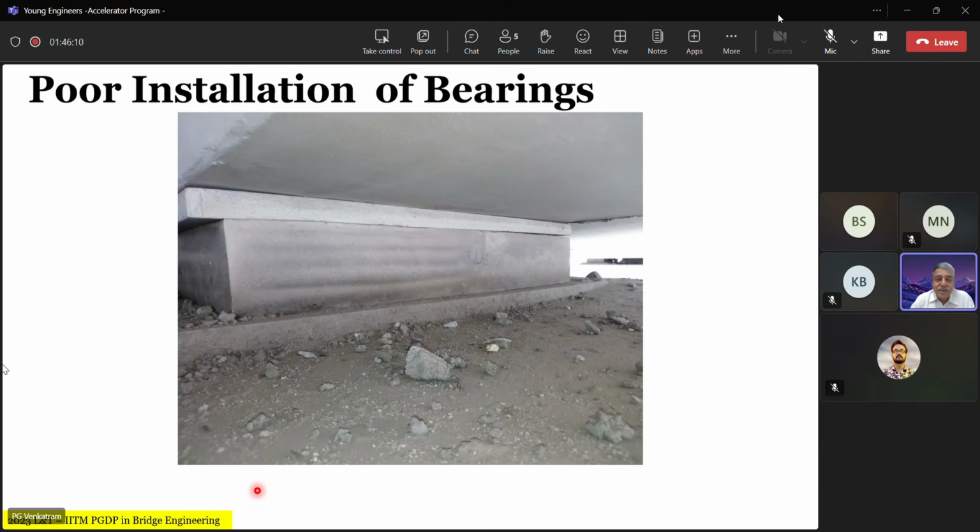Okay, I'll put it in simple English. The presence of slip is the proof of existence of tension in the strand. I can have zero slip with zero force in the strand, right? Yes. So the observation of slip is a proof of existence of tension in the strand. Because the strand is in tension, it tries to recover its length, shorten back, and therefore the slip takes place. If you recall the pre-stressing arrangement, I think all of you have forgotten that part.